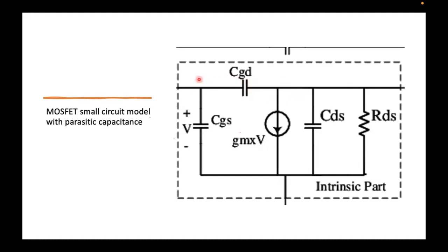So what you are going to do simply, my students, is you are going to add 3 new capacitances. So CDS, which simply impacts the overall capacitance of your filter. So CGS, we can consider this with a minimum impact to the system. And the CGD, which connects the output to the input, making this significantly important.